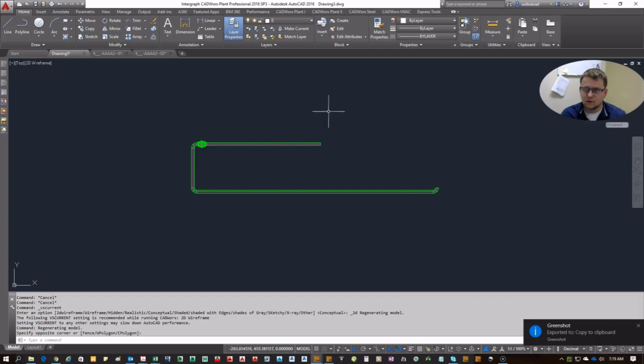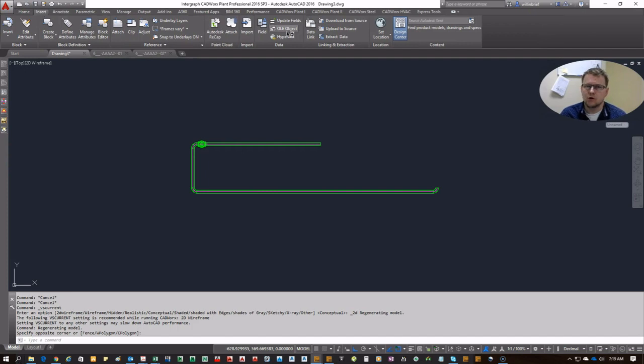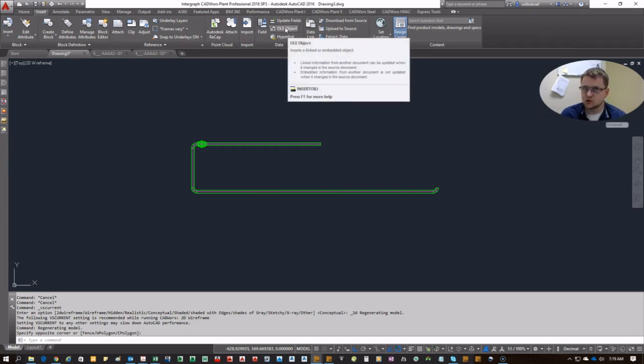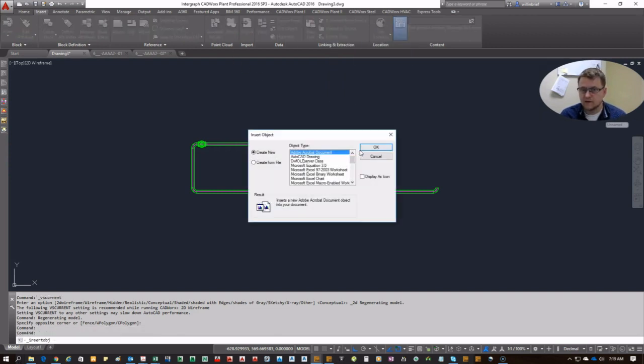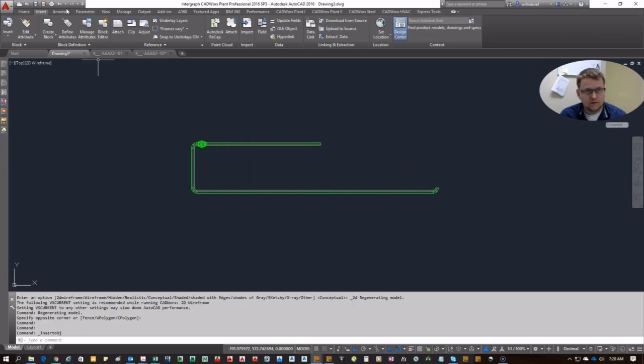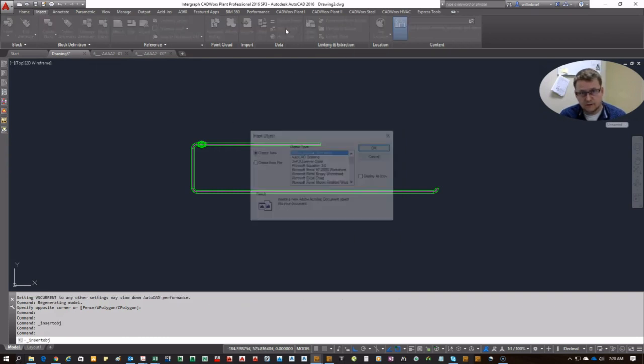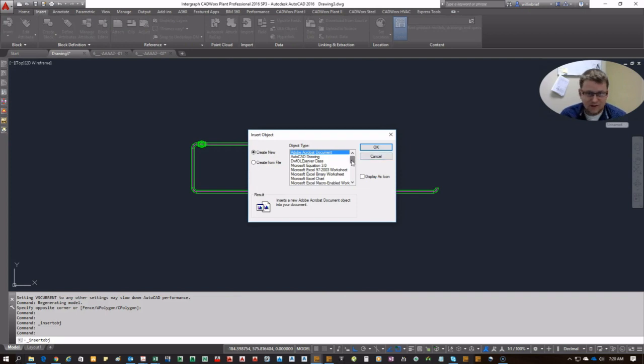Now this is going to sound a little weird the way I'm going about this. There are hundreds of ways to insert an image. This is the one I find to be the best, in that it keeps up the image quality in a way that others won't. It also allows for editing in a way that others won't. So let me go ahead and go over this. I'm going into the Insert toolbar, OLE object, and from here, it may sound a little bit backwards.